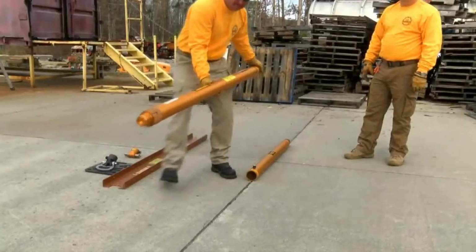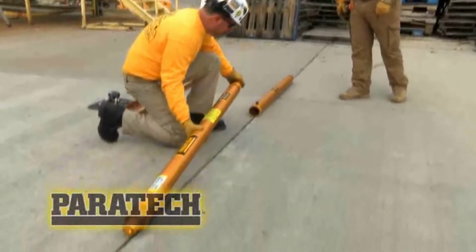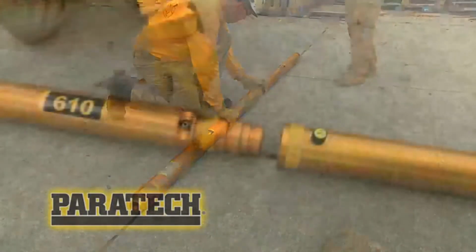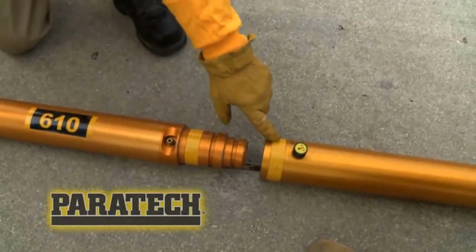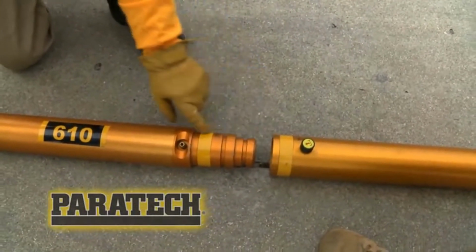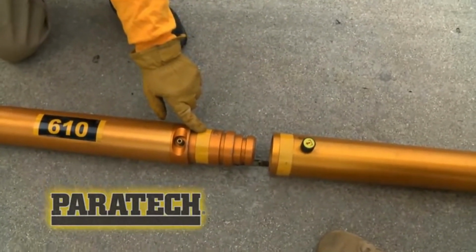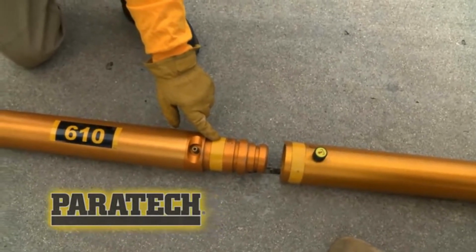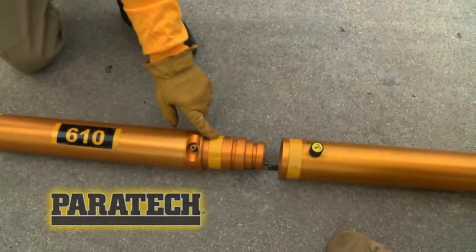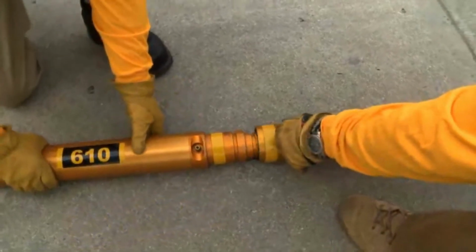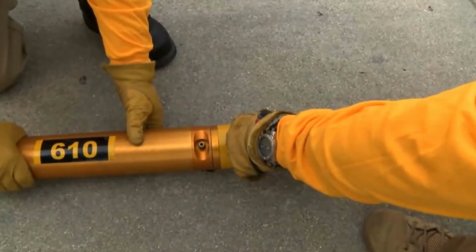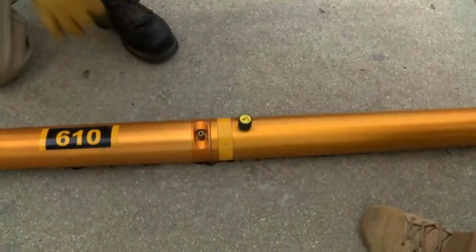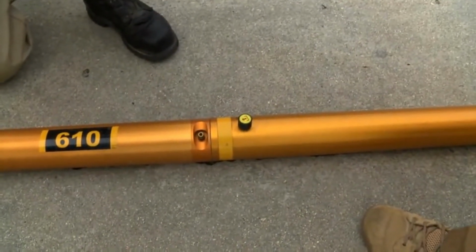So at this point, they will bring the strut down to the extension and set it down. Remember, yellow tape to yellow tape assures that the extension goes on the correct end of the strut, the non-movable end. Now assemble the two pieces. Pull up the lock pin, set it, and let the lock pin go. The assembly is locked together.